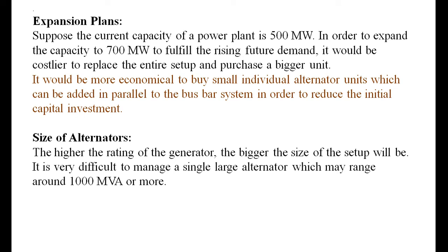the power stations are located in remote places where resources are available. As such, there is no proper connectivity to those power stations. Then in that case, if you are designing a single unit, it is a very huge size and the transportation problem is there. Instead of that, if you are using smaller units of 100 MVA, 10 units, that is catering to the need of 1000 MVA. That is more convenient than a single large unit.